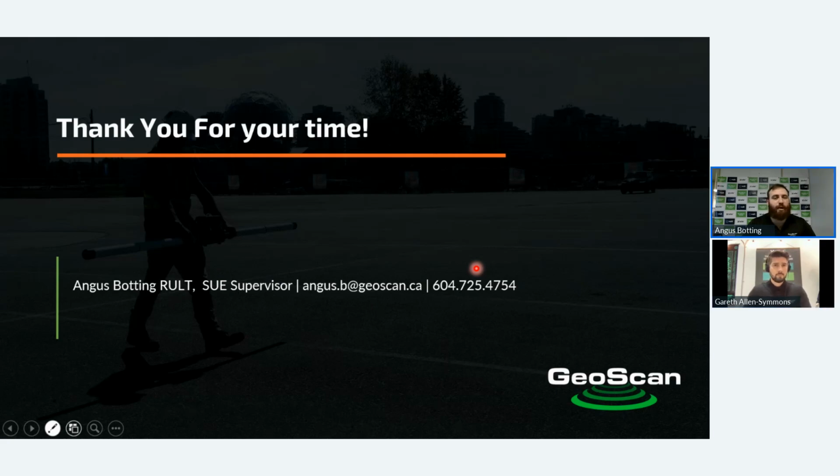So third party, for instance, if we were given a topographic survey and we went to the field to do the quality level B investigation, we tend to overlap and double check the topographic survey. We will also shoot the manholes, etc. In cases where they don't want us to do that, and they want us to bring it to level C,